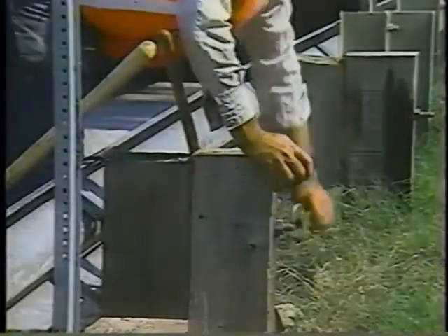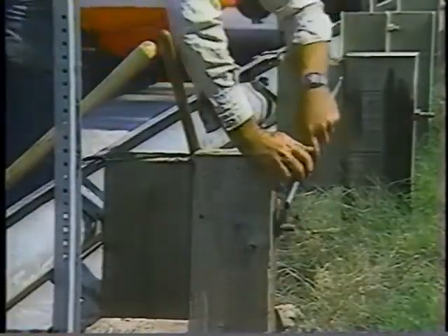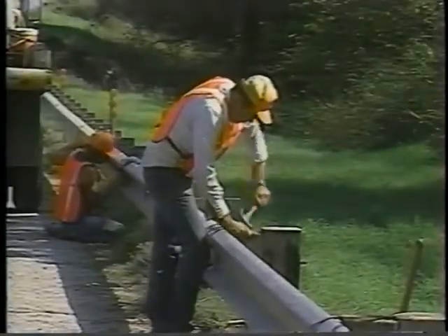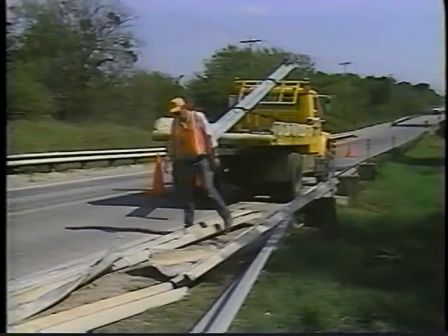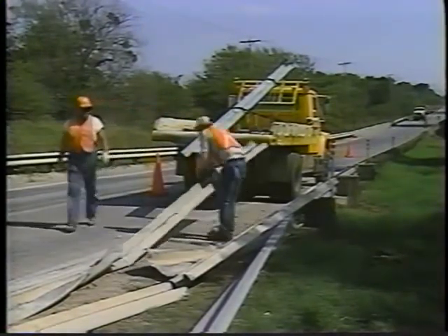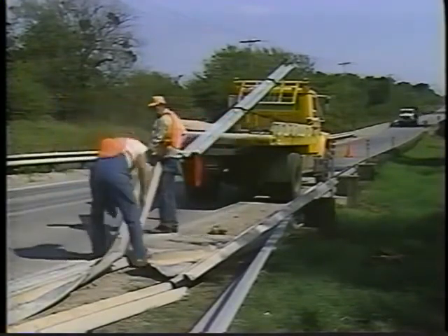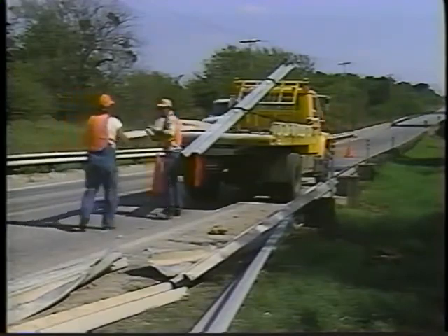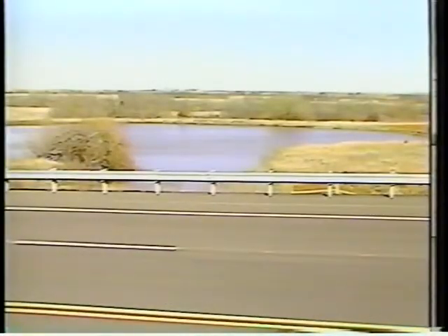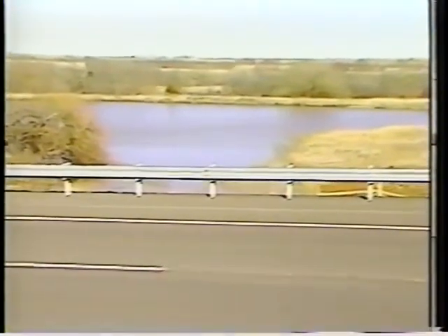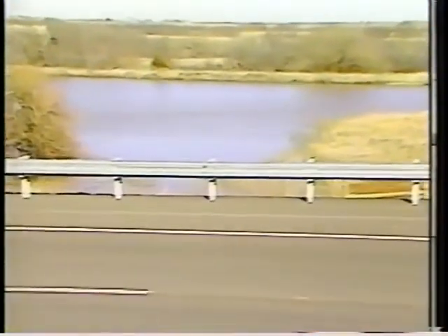When all the W-beam has been hung, all the nuts and bolts should be firmly tightened. And where needed, toenail the wood post. Finally, when all the repair steps have been completed, the work area should be cleaned up and the elements of your safety zone removed. Remember, in all repair or installation work, be sure to follow your state's guidelines. The W-beam wood and steel strong post systems, widely used as a protector for our nation's highway users.